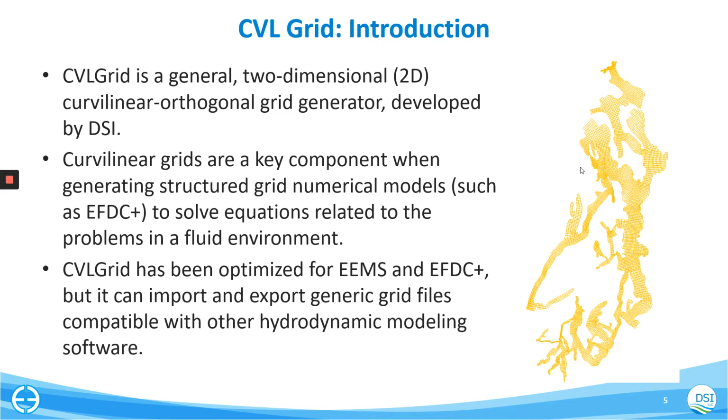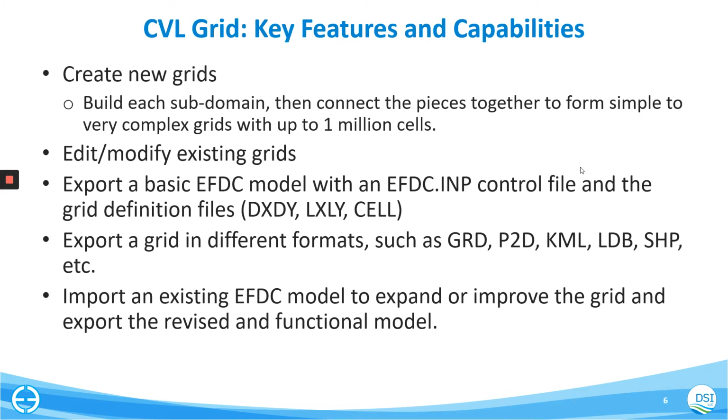Although it has been optimized for EEMS and EFDC Plus, you can import generic grid files from other software or export grids for other software. CVL Grid can help you create brand new grids for a domain that has not been divided before. You can bring in an existing grid, edit it, modify it, make a basic EFDC model, and you can export these grids in different formats, sometimes for different models, sometimes just for communication.